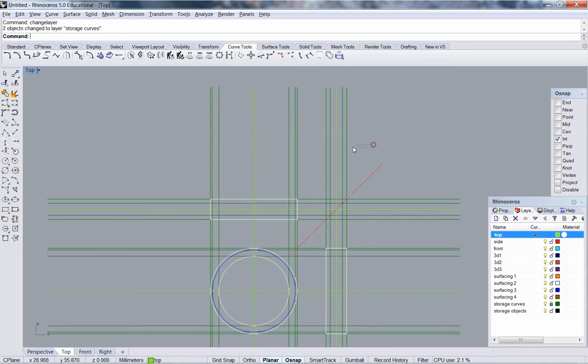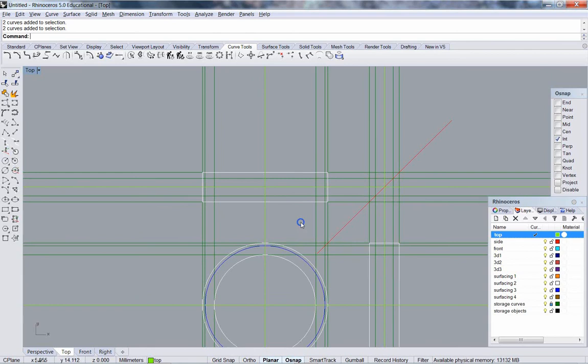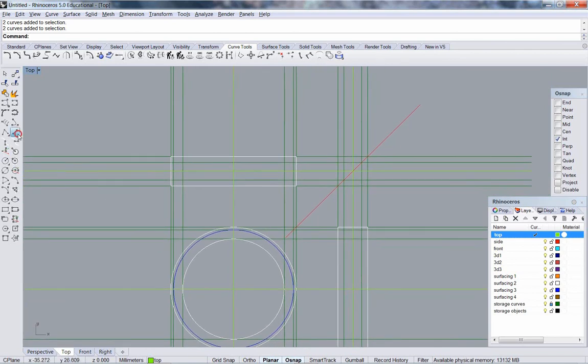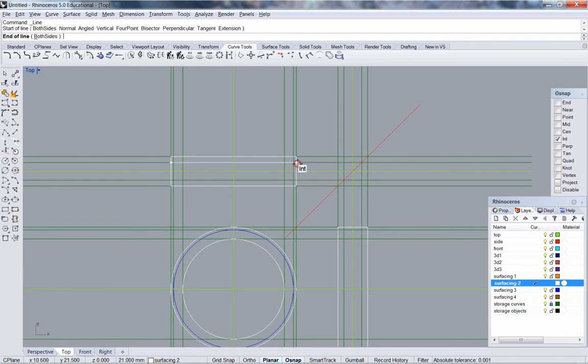Okay. Notice how when I grab this, it can't grab anything on the dark green layer. That's because it's locked. And that locking of the layer also makes it always fall to the back, so our drawing is clearly visible above. I'm going to finish drawing my top and side view so far as I possibly can. I'm going to draw my rim, my bottom rim, and where my stone tray falls away.